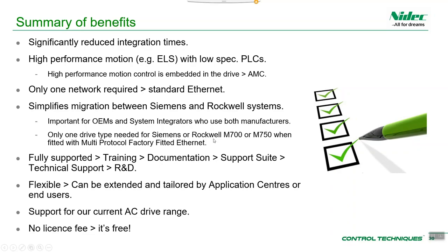One thing to note is that if you do have a system and you're working with Siemens and Rockwell, then the M700 or M750 Digitax HD drive, when fitted with the multi-protocol factory-fitted Ethernet module, is able to work over Profinet Ethernet communications, and it's able to work with EtherNet/IP communications. So no matter which PLC you're working with, you only need one drive to be able to work with either of those communication protocols, which is quite helpful.